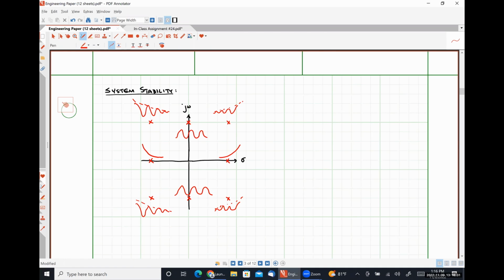And then obviously, if you design a system with poles on the right-hand side, it's just astable, right? You have designed a system that is meant to go towards the supply rail in one way or another, which for things like an astable multivibrator. Exactly right, an astable multivibrator circuit. That's literally what I was trying to think of when we talked about that. I think we covered that in circuits too for all of you guys using an op amp based design. The purpose there is literally, you have no input signal and yet you get out an oscillation, okay? So noise is capable of sustaining oscillation in perpetuity, okay?